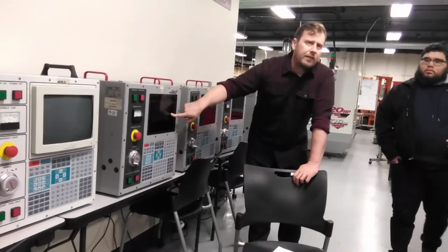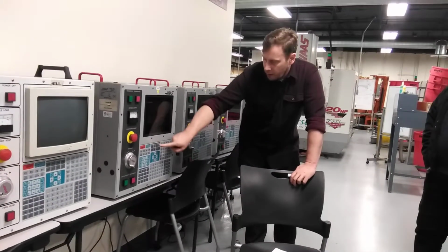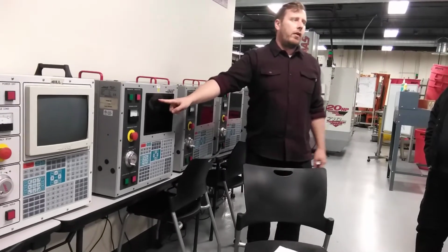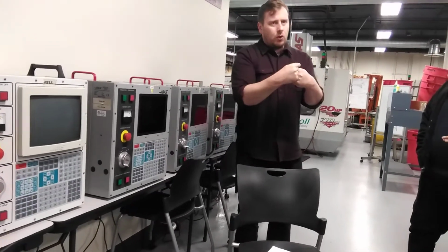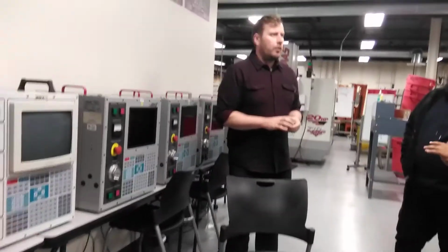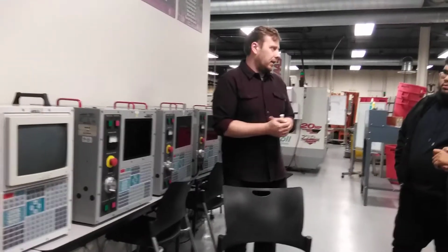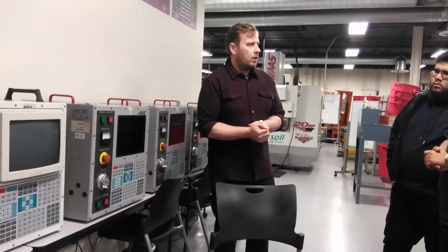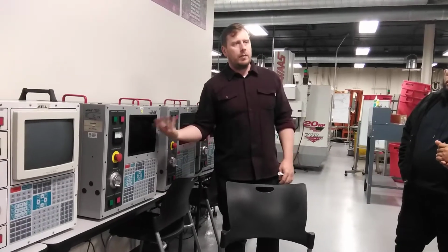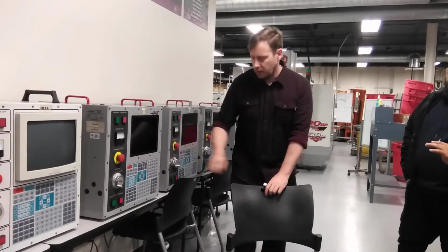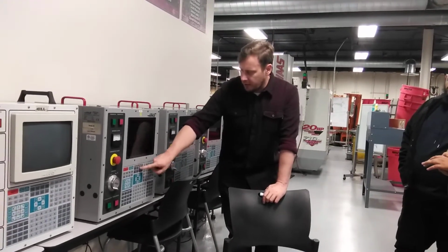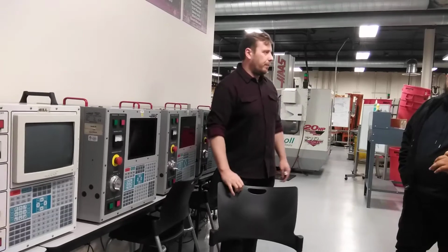The old tool used to have it in radius. When you go to the offset page, now it's in radius. So you have to measure your tool, divide it by 2, and then enter the number. The more math you're going to do, the more likely you are to make a mistake. That's why it's best just to have it in diameter. Whatever you measure is the number you input. So it is possible to change it, but it's a lot easier to work in the diameter page.